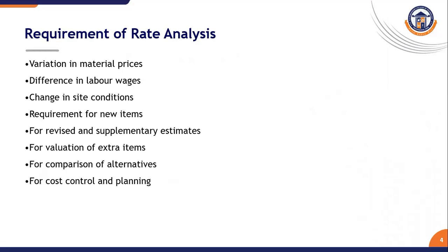Requirement of rate analysis. Rate analysis is required because the cost of material and labor varies from place to place and changes with time. It is also required when new items are introduced, when site conditions change, and when revised or supplementary estimates are prepared. Rate analysis helps the engineer to evaluate the extra items and plan construction activity economically.